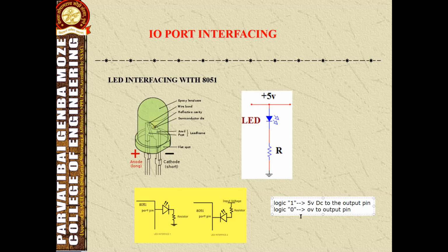The LED in common cathode mode can be connected to the 8051 with a resistor here. The common cathode is used here. And why are we using this resistor? If we connect VCC directly, a high voltage will occur. Due to the high voltage, there may be a chance of burning the diode. So to drop some of the direct voltage, or to avoid burning this LED, the resistor is connected.